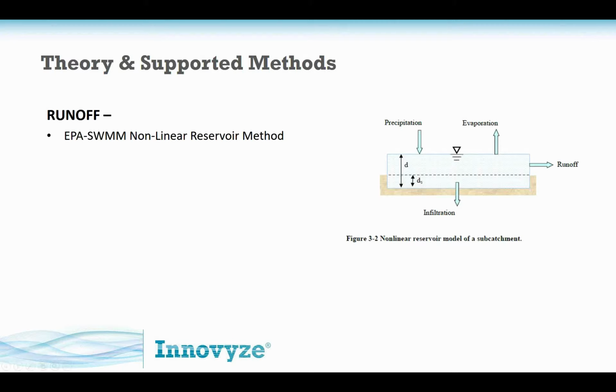I think the most difficult thing that modelers get into, especially early modelers, and this is an introductory class or webinar, is how do you take a natural catchment and idealize it to this reservoir model, which is assuming a rectangle. I think that's probably the most difficult thing we have in adopting runoff.